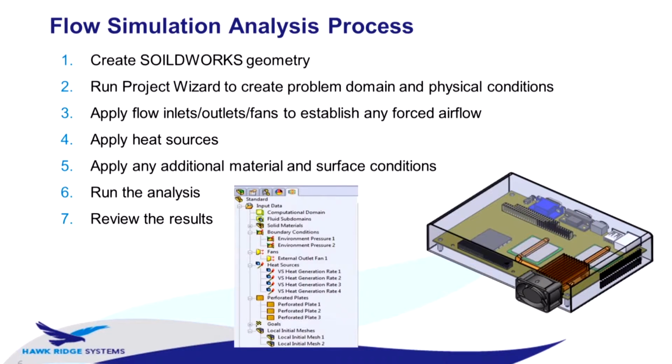And we'll even be able to automate that process a little bit if necessary, where we could examine a large batch of design options all at once, or even run an optimization mode where we could look for the best value of something, like the best value of a wall thickness dimension, or a thickness of a heatsink fin, or how many fins you have, or even dimensions to locate different components throughout the model.